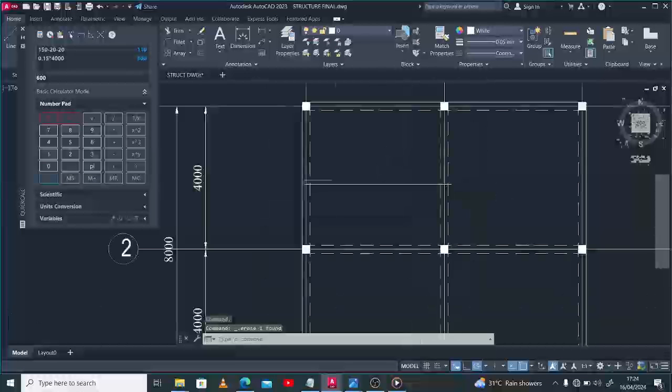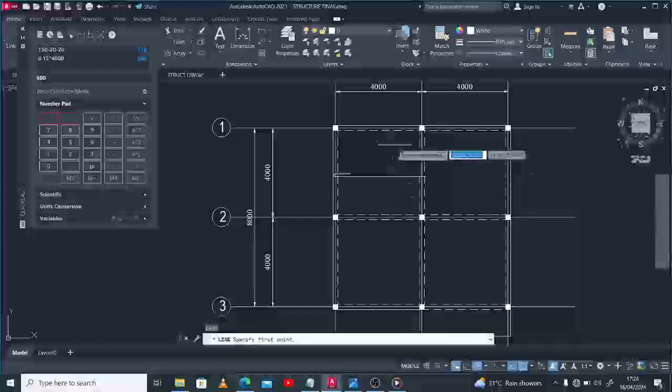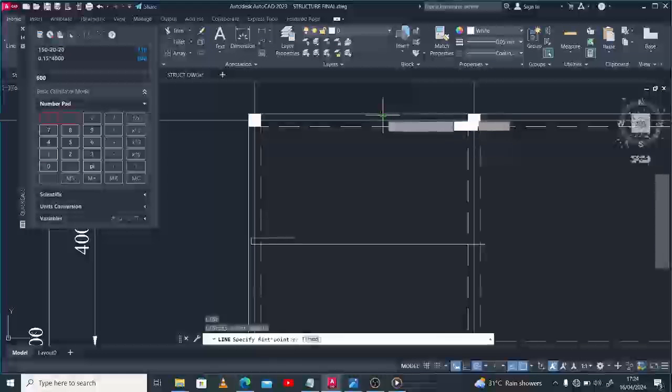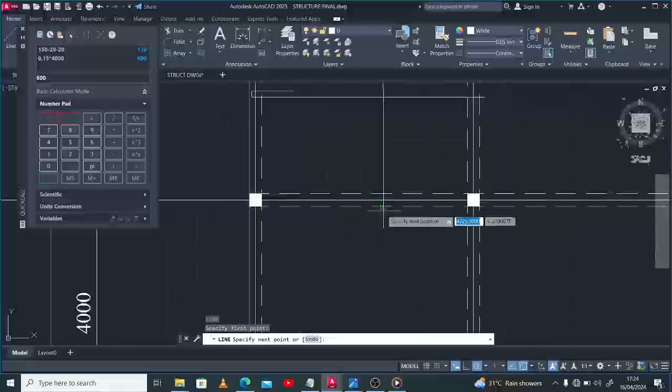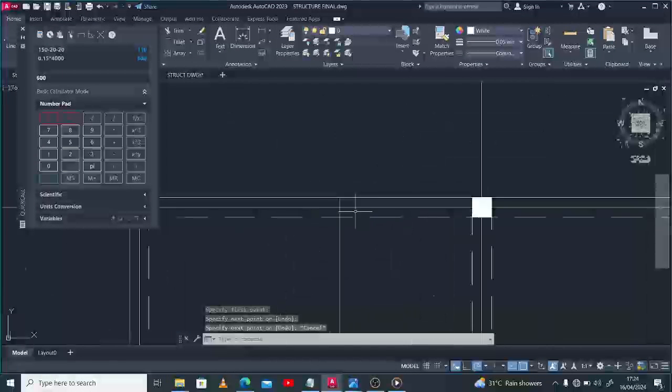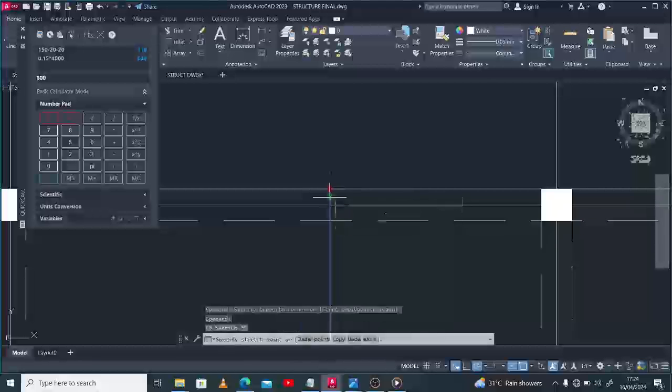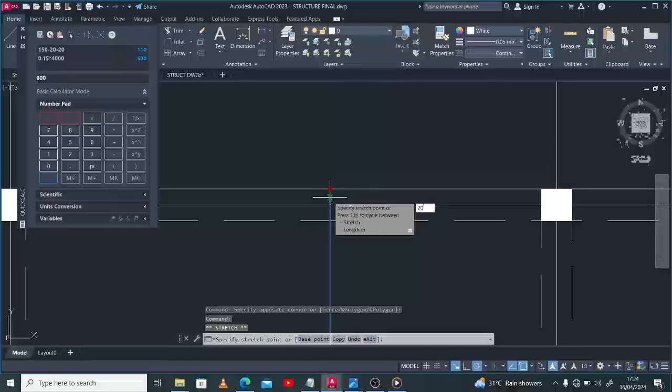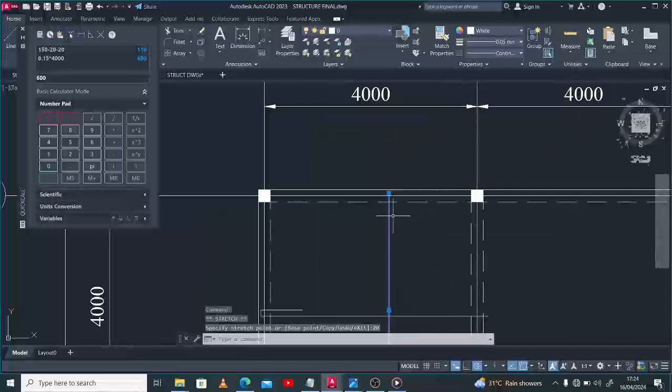All right, thank you. So on the other side, the same thing applies. You have a reinforcement spanning all through to the next support. Then you take note of the cover, and this cover is for the purpose of keeping your reinforcement safe from exposure conditions.